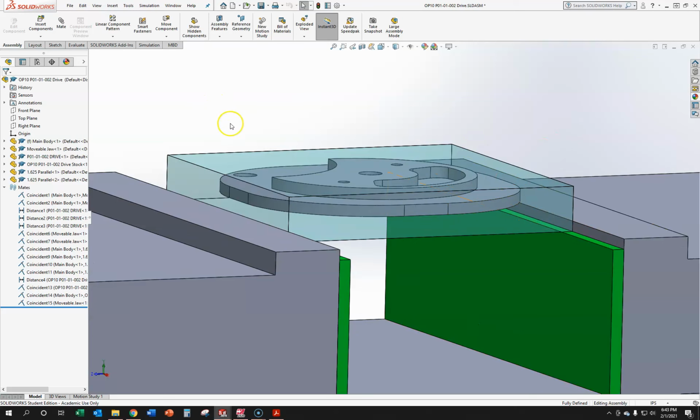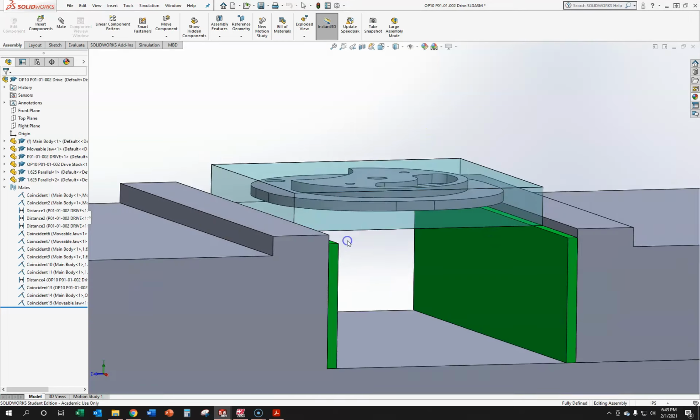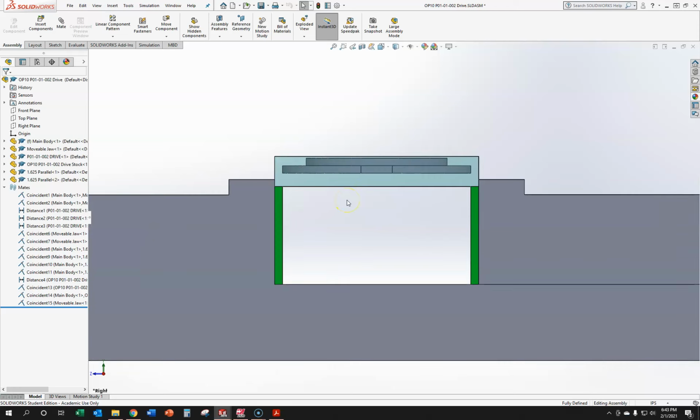For this, especially when you're face milling, when you have a lot of surface area, when you have a large tool on the part, you risk throwing the part out of the vise. So I don't think I want to go back and fix all that. We could.